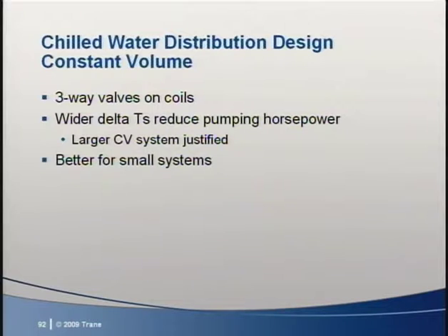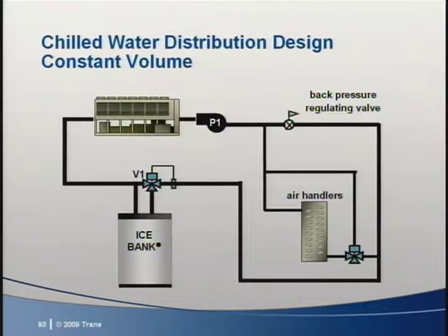In constant volume systems with 3-way valves, ice can be beneficial if it allows for a wider system delta T. The pumping horsepower may be reduced enough to justify a larger constant volume system. But still, constant volume systems are probably best used in smaller existing systems.